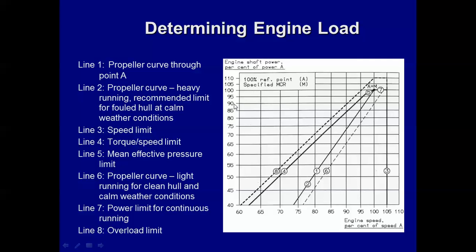So I'm referring to my load indicator and my propeller RPM, and let's say I'm right up in here. Now, let's say we go into a storm, and actually let's pick 85%. So let's say I'm at 95 RPM and 85 on my rack. So I'm right about here.